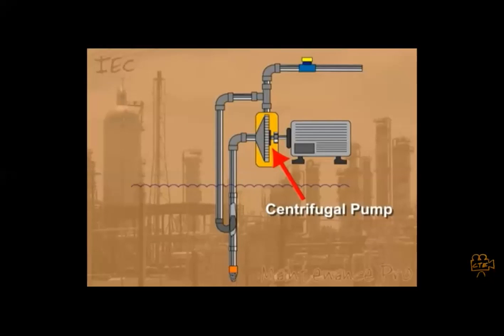So what is the limitation of that? 10.2 meter. To remove the limitation, what we have done is that some amount of water is always in recirculation mode, to remove our limitation of 10.2 meter. So everyone got this point, or you can write this point also, jet pump. Everyone got this point, yes or no?